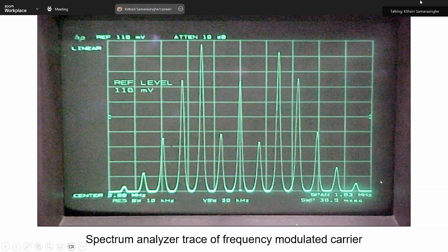Remember that, right? FM signal is bandwidth hungry. Takes about 6 times more bandwidth than an AM channel. To put it in a different way, you could have transmitted information of 6 different AM signals within the bandwidth of 1 FM channel.